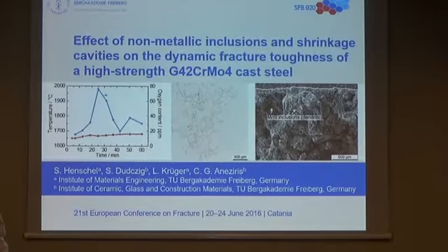So, as you might know, non-metallic inclusions can originate from wear of refractories or the melt treatment, and especially aluminum originates from the deoxidation treatment, and together with the dissolved oxygen it forms alumina in the steel melt. And in the solidified steel we have then the detrimental effect of the non-metallic inclusions in terms of deformability and toughness.